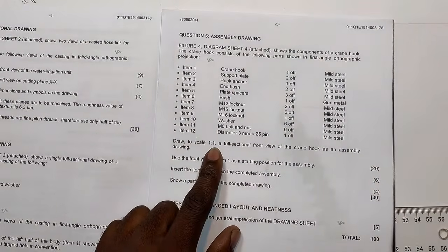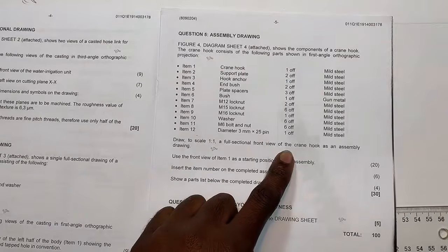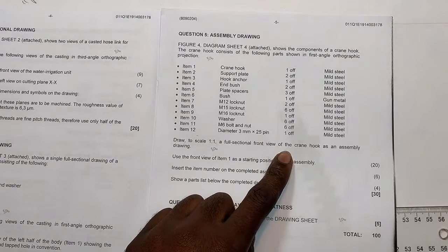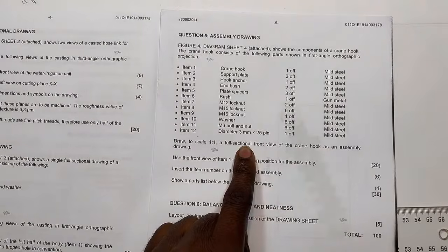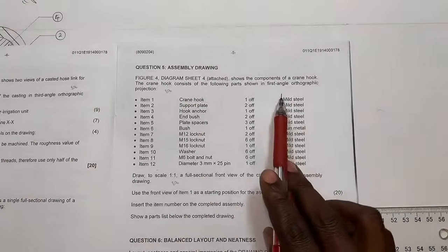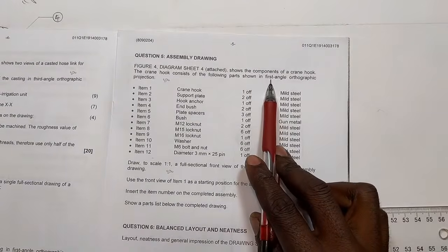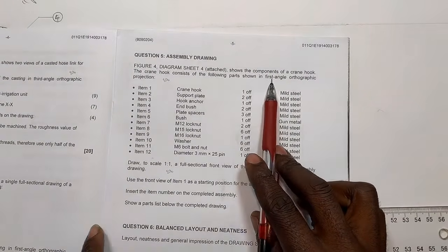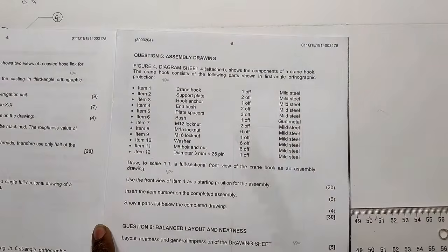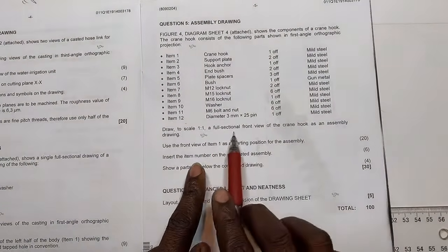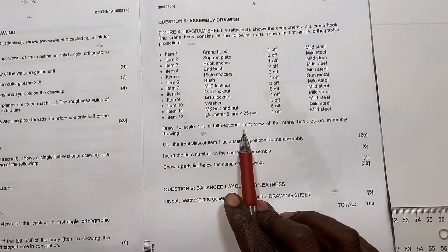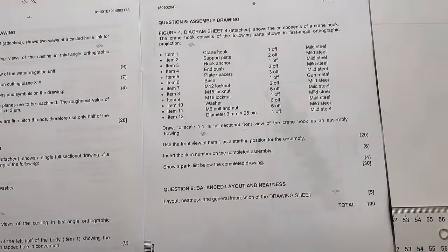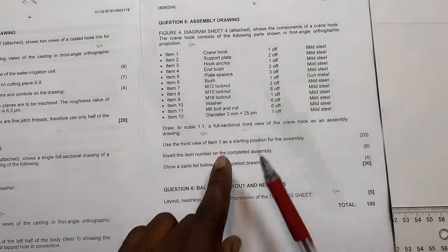When you go down there, it says draw to a scale of 1:1 a full sectional front view. It is very much important to read the question. Don't just look at it and assume it's full. Sometimes they will say draw a half sectional with the right hand in sectioning. The question says first angle orthographic projection. Remember, in first angle orthographic projection we do not have the word right, but when you read the question it's going to say with the right hand in sectioning. It takes somebody who understands sectional drawing, first angle and third angle half sectional drawing. Here they are saying full